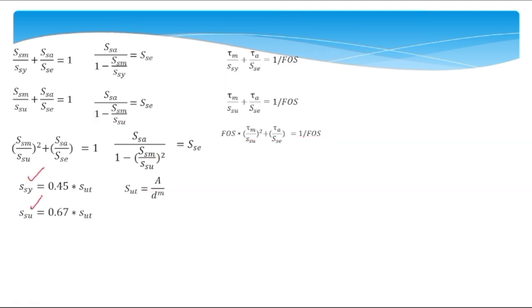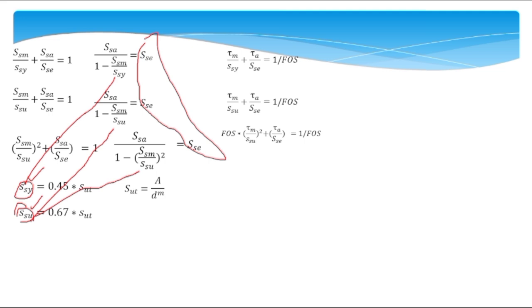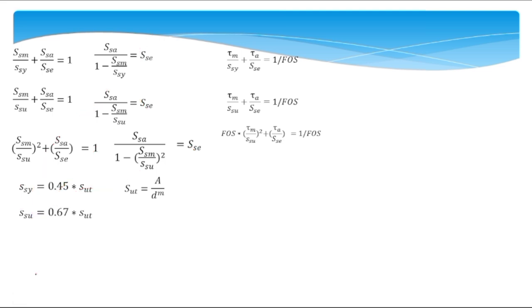So using these equations, we can find the values of SSU and SSY, and when you put SSY and SSU in this equation or this equation, we can find the value of SSE for different criteria. This is where the work of Zimmerli's data is finished. After that we will not use Zimmerli's data anymore. So we have found SSE, SSY, and SSU.